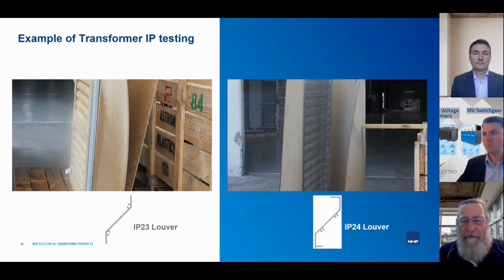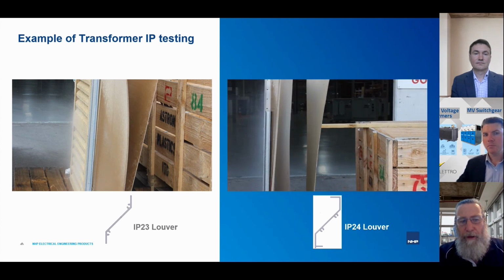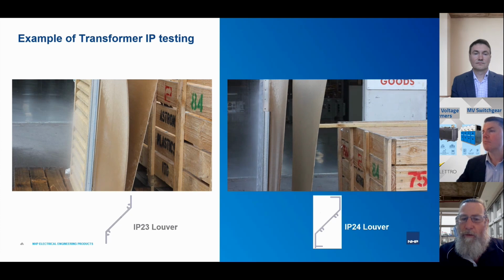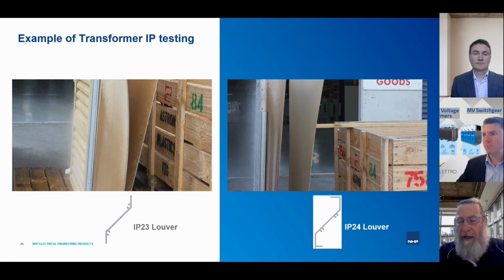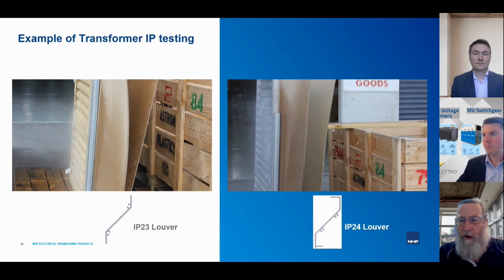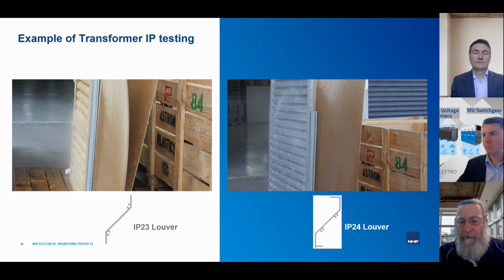But to give you a fuller picture, the transformer for West Wind had been temperature rise tested outside of the enclosure, temperature rise tested inside the enclosure, and then delivered at 100% full rating.